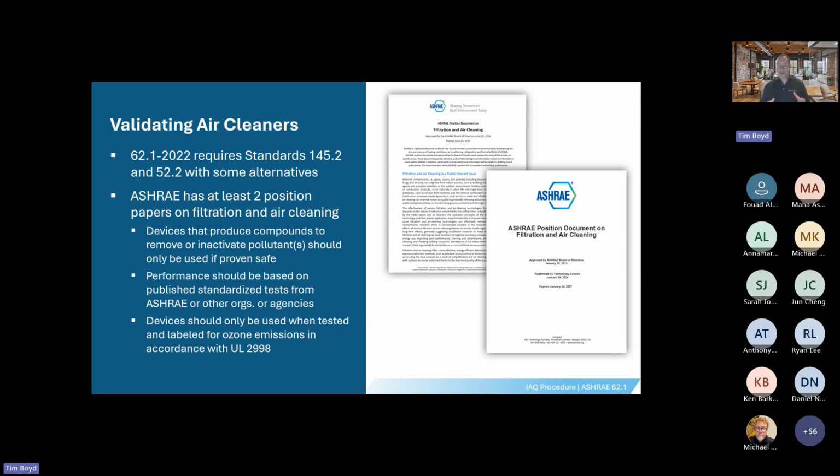If the air cleaner is creating any ozone or any other reactants, it will react with the limonene. So limonene by itself is innocuous, but in the presence of ozone and other highly reactive compounds, it will fragment and create formaldehyde. And formaldehyde, as we know, is a carcinogen. And so that's the second test. There's no additional air chemistry. And then the third test that it has to pass is a no additional particulate test. It's a clean lab test.